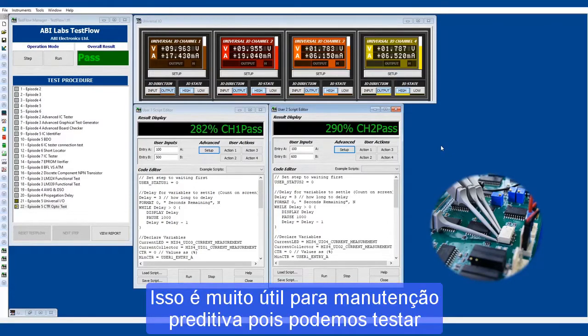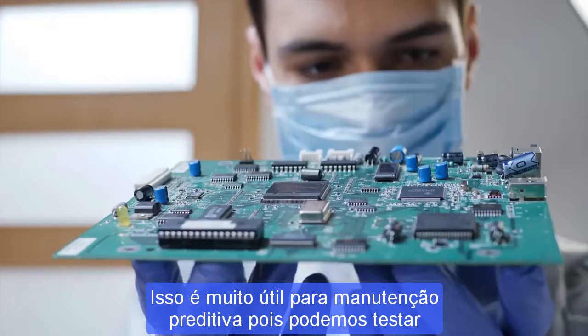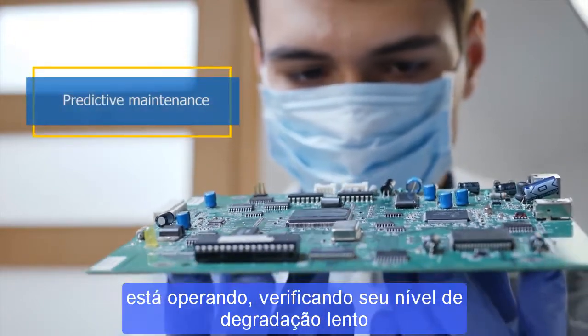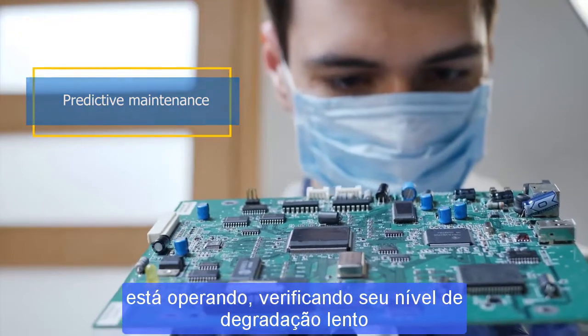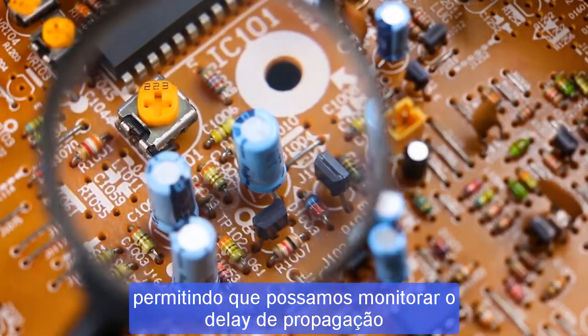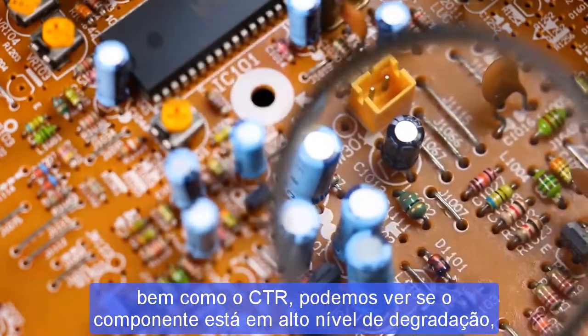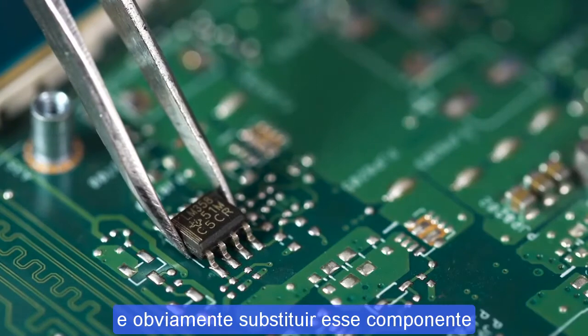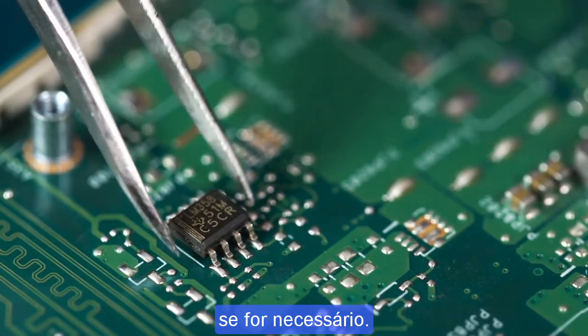So that's really useful for predictive maintenance, because what we can do is test our component and see how our component is operating and whether it is degrading slowly. By monitoring the propagation delay as well as the CTR, we can see whether our component is coming to the end of its life. And then obviously we can in time replace the component if necessary.